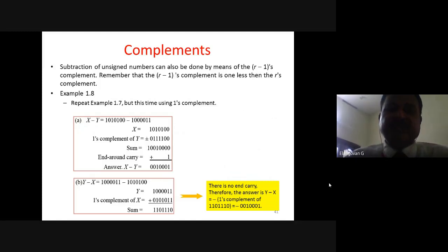And here, if you look, 1's complement and 2's complement are doing the same, but there is a simple difference. In 2's complement, if there is a carry, we simply discard the carry. But in 1's complement, if there is a carry, we do addition one more time. So in many systems, the 2's complement is preferred rather than 1's complement. But still, both complementing methods are used in different kinds of discrete units, either in the whole system or in part of systems.